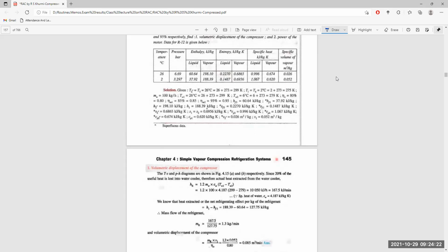which is the enthalpy of our refrigerant at the fluid stage at point 3 itself. hf3 is the enthalpy of the refrigerant at point 3 at the exit of the condenser, which means it is the liquid enthalpy at the higher temperature or condenser temperature, which is 60.54, not 64, but 60.54 itself.